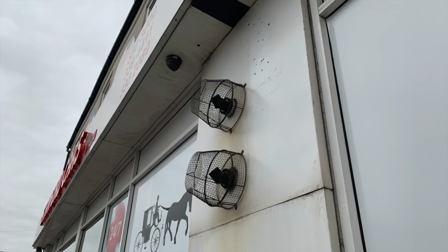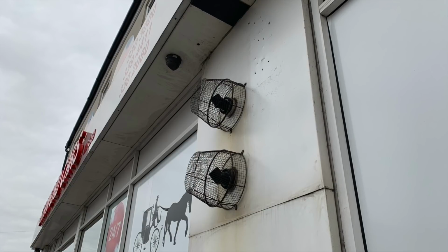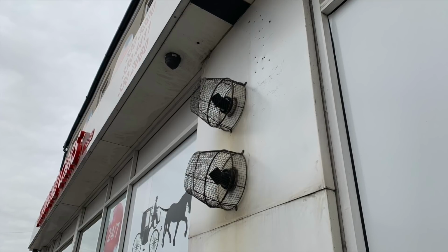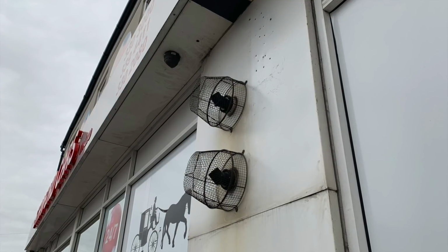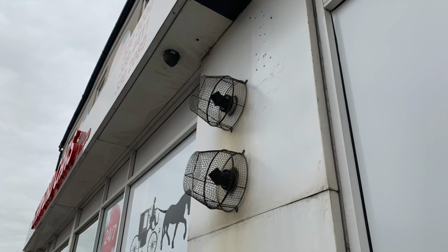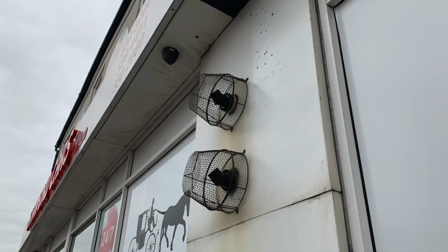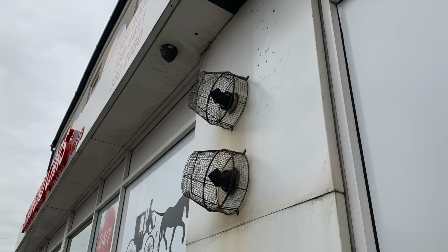Now I just said you can't get it wrong. Well, how wrong can I be? So we've got two Worcester flues here, one directly below another, and according to Worcester's manufacturer's instructions, these need to be 1.5 meters apart. And you can see they're not. And I have no clue why there's terminal guards around them, because they're way above 2 meters.